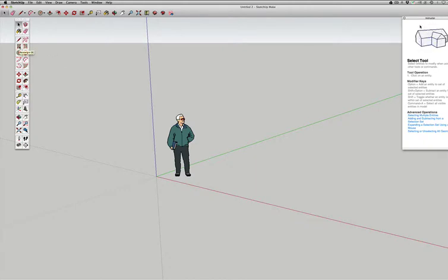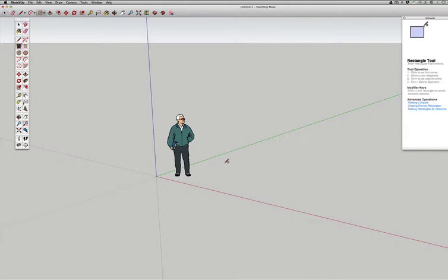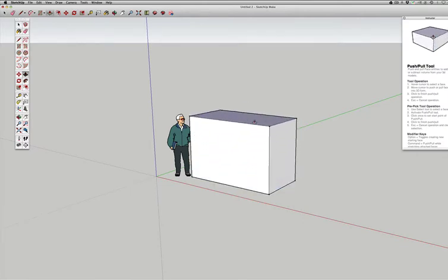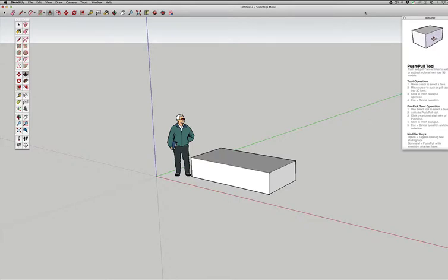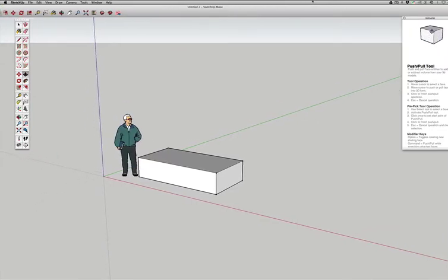All right, so we're going to do a rectangle. Not surprisingly, for rectangles you can hit the letter R. Pull it out, and boom, there it is. And obviously hit P for push or pull, and boom, there you go. All right. Now, what you might not know, and I'm going to put it right over here so you can see this edge, right down there says distance.